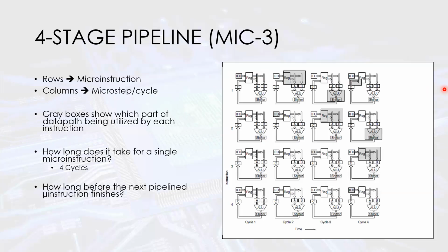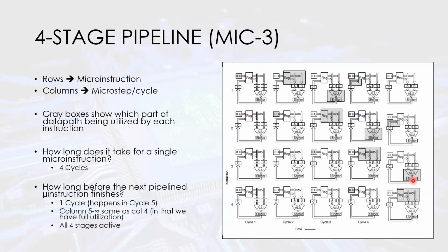This is the whole concept behind pipelining, right? It's just 1. So it's going to take 4 cycles for that first one to finish, but from there on out, you're pumping them out. Every cycle, you're going to have the next instruction finishing. Now that's ideal, right? We just showed that that's not always going to happen because of dependencies or hazards, if you will. Okay, and then columns 5 through infinity are going to be pretty much the same thing. We just keep on going with that.